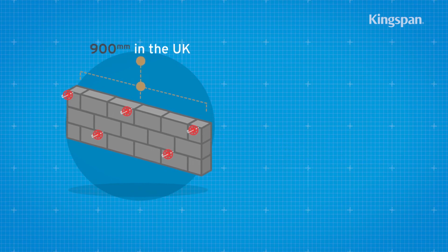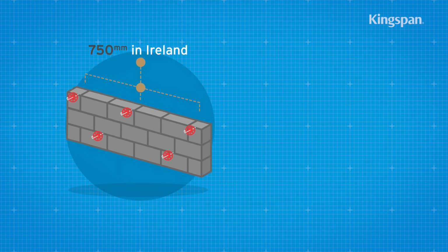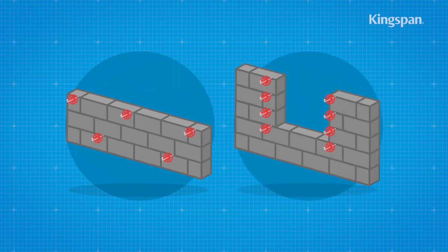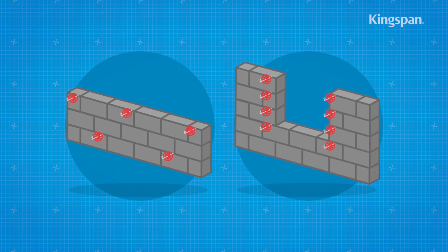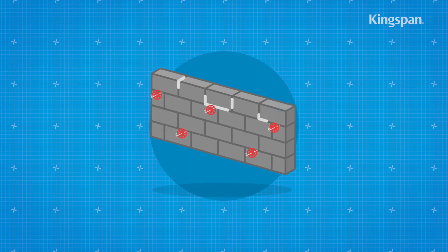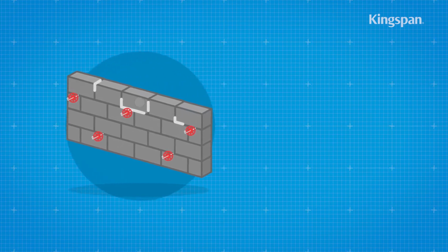The next course of wall ties is positioned at regular horizontal centers. Extra wall ties should be positioned at jambs for all openings. The next course of blockwork should then be installed to secure the ties.